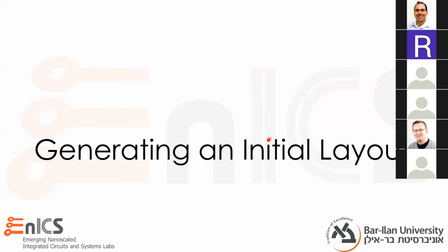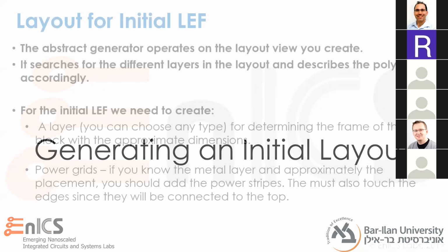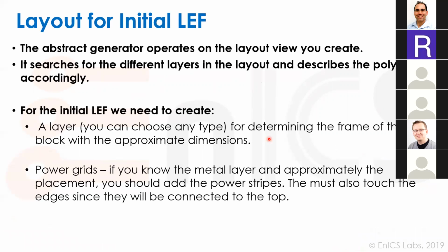So I will talk mostly about generating the initial layout, which is the one we'll extract for the initial LEF. And when we finish the final layout, it's the same process as this one. But for the initial layout, there are a few things that we need to know before we do this. So, I'll talk in a bit about the abstract generator. The abstract generator is the tool that creates our LEF.